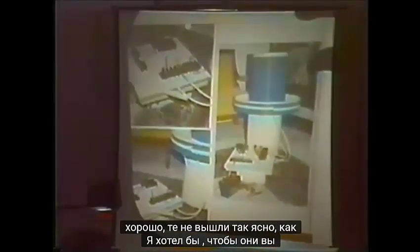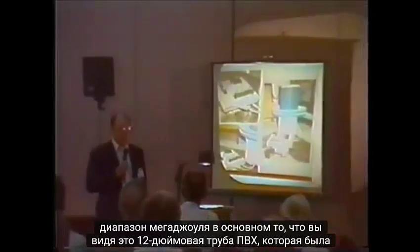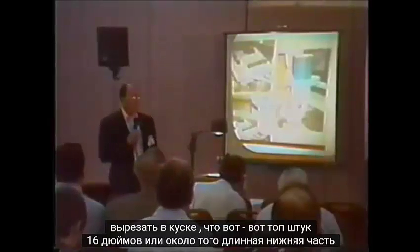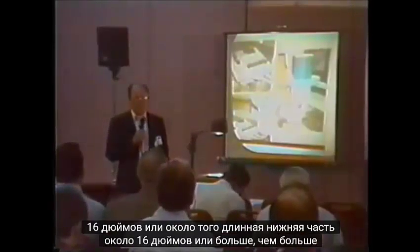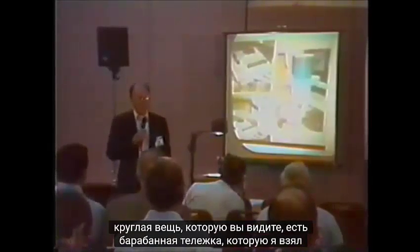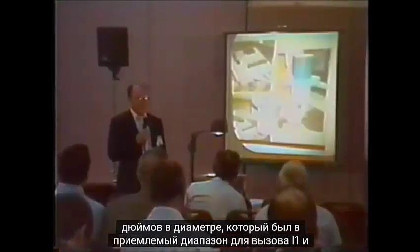Okay, those did not come out as clear as I would have liked. You're looking at one there that's in the megajoule range. Basically, what you're seeing is a 12-inch PVC pipe that's been cut into pieces, the top piece about 16 inches long and the bottom piece about 16 inches long. The larger round thing that you see there is a Rubbermaid drum dolly, which I took the rollers off of. It happened to be 25 inches in diameter, which was in the acceptable range for the L1 coil.